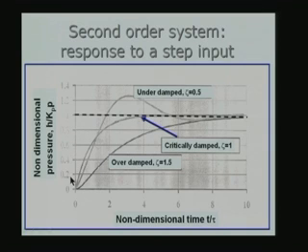The numbers here are not very clear, but I will just read them out. On the time axis, I have taken the ratio of t to the characteristic time, t by tau, plotted from 0 to 10. On the non-dimensional pressure axis, which I call h divided by Kp into p, the height is non-dimensionalized with respect to the forcing function. Kp into p is the value which is input, and h is the height of the column. If the system were to have a very fast response, it would immediately go to this value. Of course, because the system is damped, whether underdamped or overdamped, there is certainly damping.